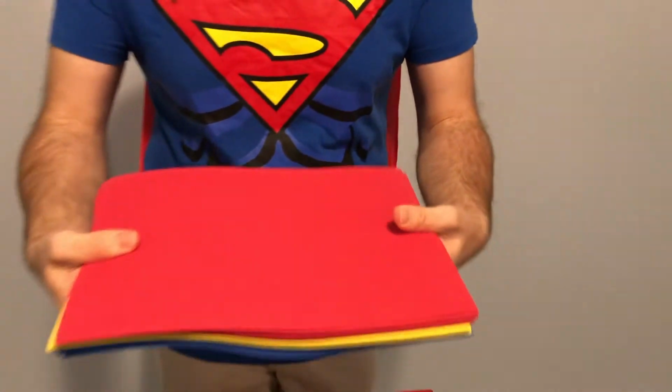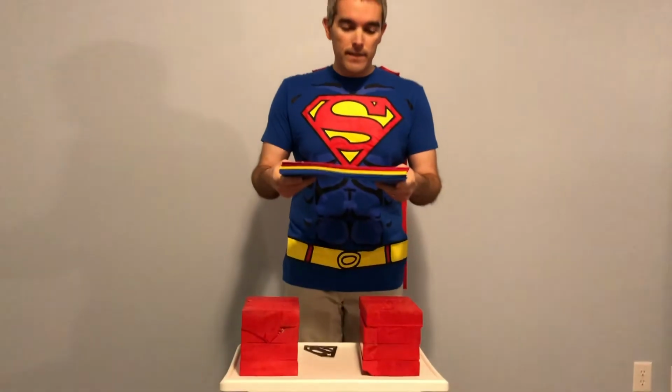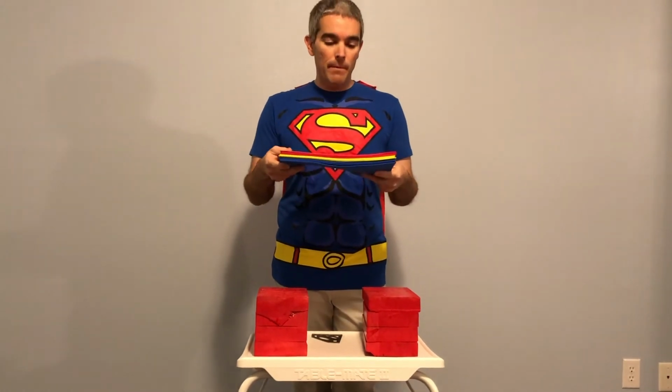Basically that happens because these layers are all individual pieces, so they don't have any means to pass that shear stress. You remember we said that when beams deflect, they have a shear stress in the longitudinal direction along the length of the beam. If you have an unbonded system, then the individual layers don't really work together. They can slide relative to one another, and that's why we see that movement at the side.